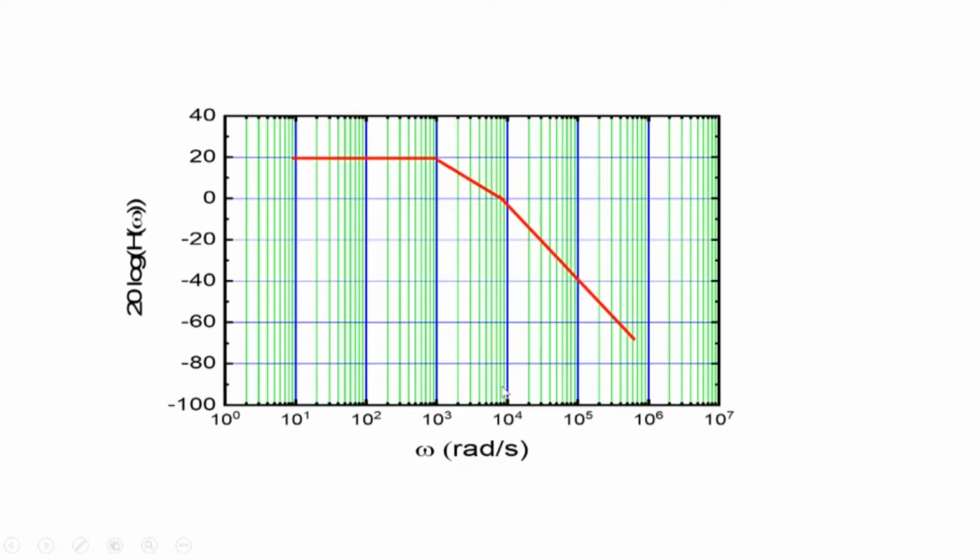And let me superimpose the exact function here, calculated here. So the blue one is the exact function, and you can see here that our approach of sketching the transfer function using these piecewise linear segments is a reasonable approach. It captures the magnitude part of the transfer function quite well here. Okay, so it's a simple and useful approach for seeing the characteristics of my system.